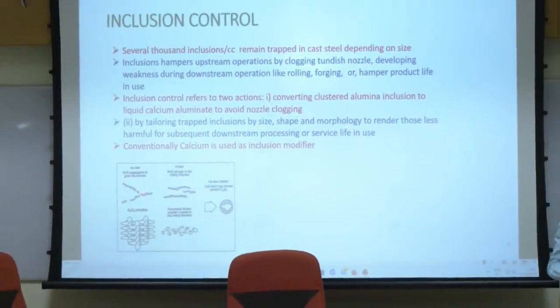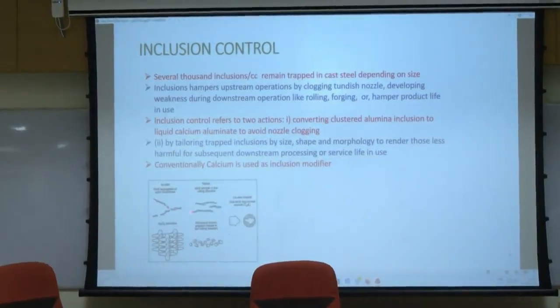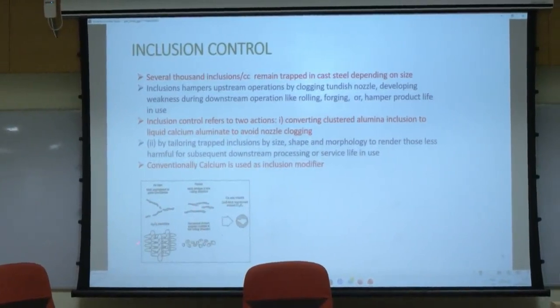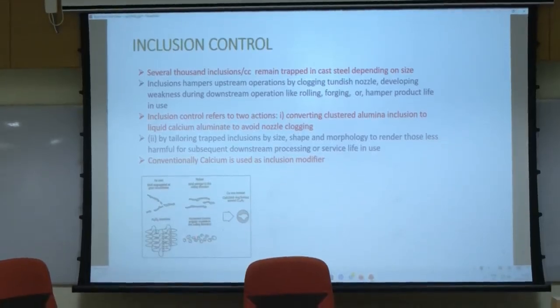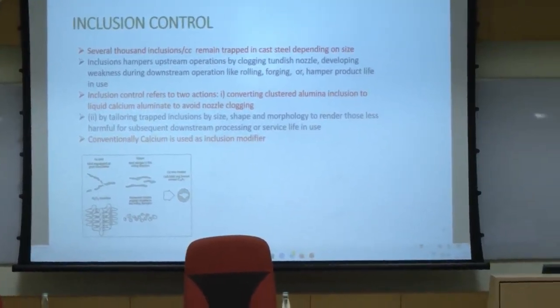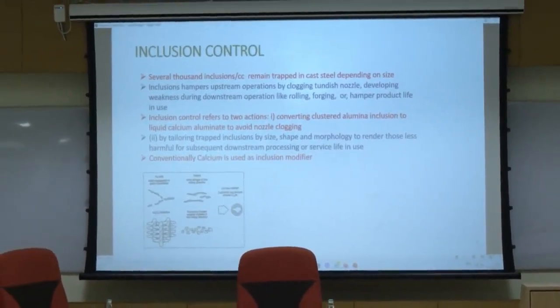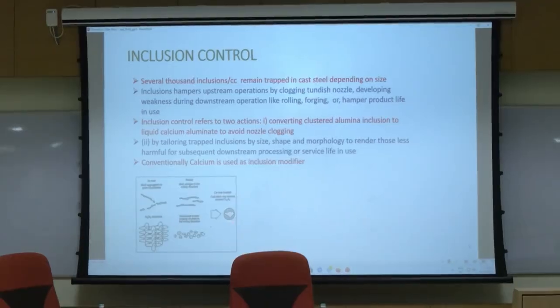And what does it modify? Basically, you can see this is the alumina inclusion, and manganese sulfide also. They produce a lot of anisotropy after rolling, and after rolling the alumina inclusion looks like this. They are very hard. Basically, they cannot accept any energy. All the energy they transmit at the interface, as a result, they act as a stress concentrator.